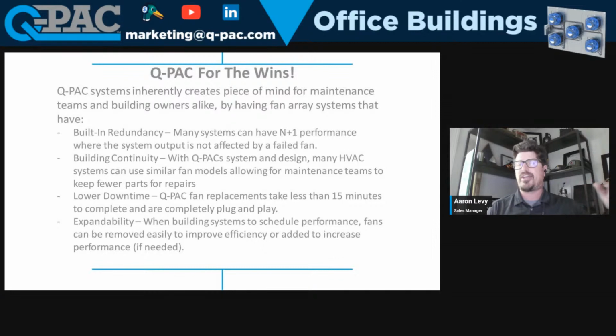They were talking about expanding a building over the course of the next 7 years, another 3 floors. So the way the bid was going out, they wanted to have all that equipment at one shot. My concern, in my talk to them, was that instead of my competition building you a 60,000 CFM array that's going to go into a building whose 3 floors aren't even built yet, you'd have this giant system that's not really collapsible. We could build a system that is expandable over the course of your next 7 years.